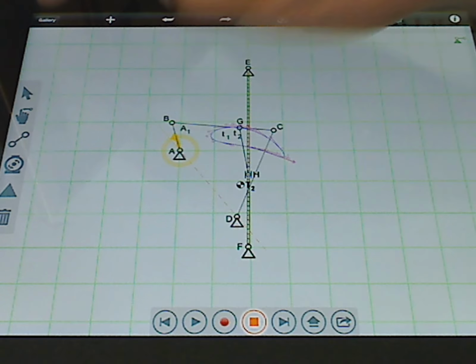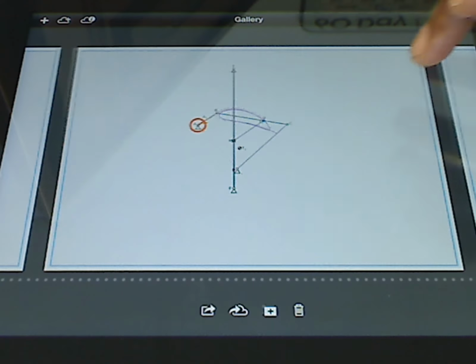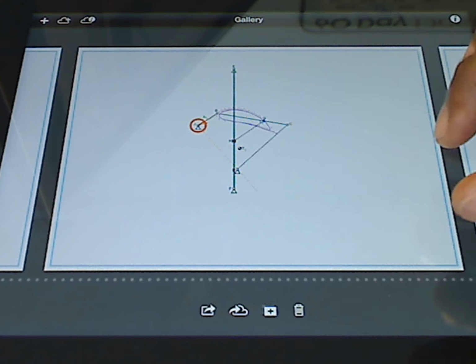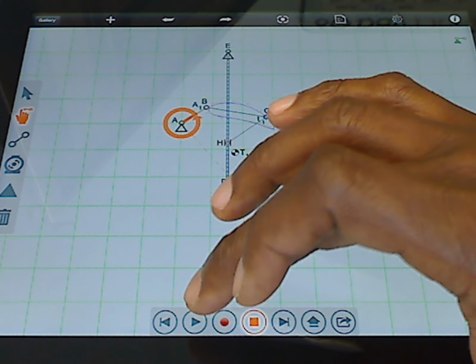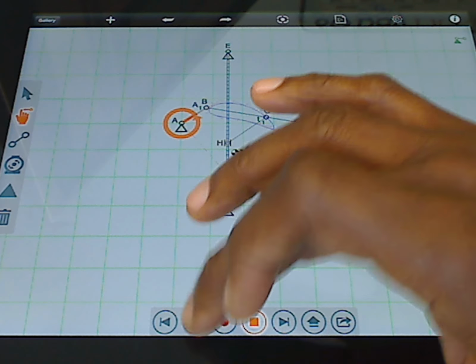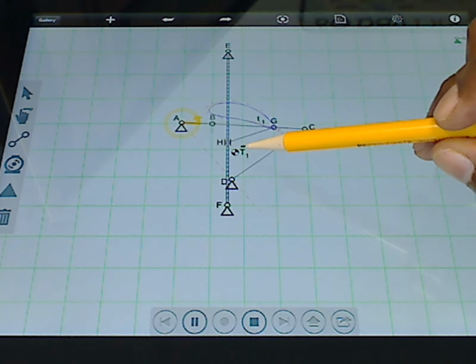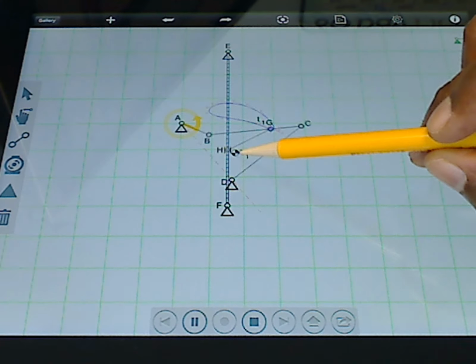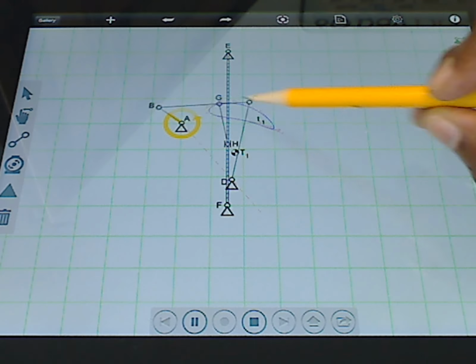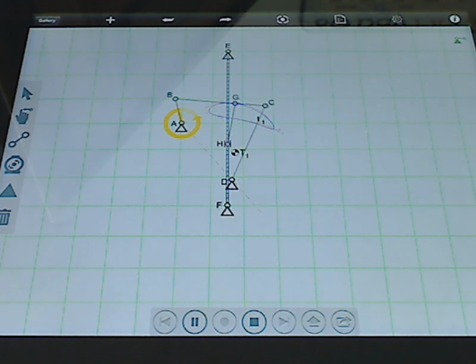And so my next rendition of this, the same thing. It's a little bit more careful trying to find the center. And I found the center this time to be a little bit further over. And this time we can see that we're going to get a lot more dwell this time for about the period of time that we wanted. And let's watch this. And so as you can see this time, there's our maximum, and we come up, and right there we're stopped. And we're dwelling. Now we're coming back down, maximum, and then here our dwell starts about right there and goes over to about here. And so that's pretty close to what we saw in the example in the notes. And so you can see there that we're getting a pretty good dwell.